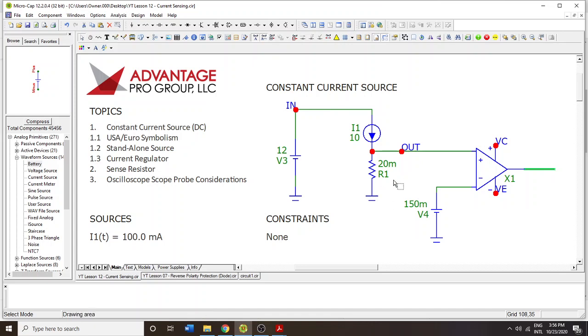So if the voltage here at 200 millivolts is higher than the 150 millivolts, then I'm going to indicate some sort of true condition, and that might give me a way to detect if I have an overcurrent condition, and that's often how it's used, is to indicate overcurrent.